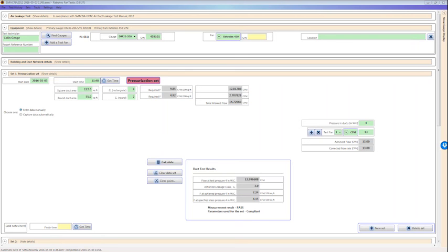No, we did answer David's question directly online, and that is, people ask, well, what do you do when no matter what system you've got, you can't achieve pressure or you can't even get anywhere with extrapolating? If whoever you're working with, if this is their first time doing a duct test and it's yours, you're both going to have a learning curve. Believe me. Most of the installers know that it's going to be tested, and they will already set sections up into chunks that they know will be tested. Nobody assumes that you're going to come out and test an entire system.